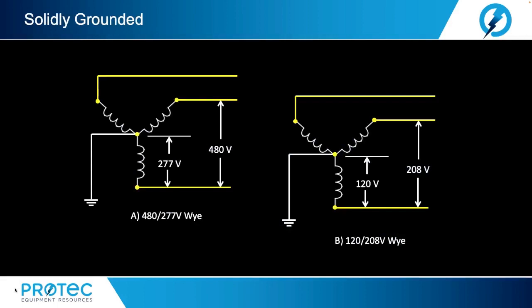All right, let's move on to solidly grounded systems. Solidly grounded systems are commonly found in industrial and commercial power systems, where grounding conductors are connected to earth ground with no intentional added impedance in the circuit. In many cases, solid grounding, National Electrical Code Article 250-5, is mandated. In others, it is selected based on economics.